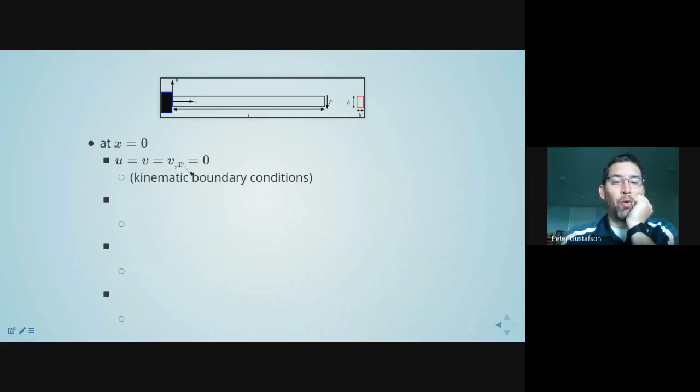And in this case, I'll make one more statement, and that is the slope. This is the derivative of y with respect to x is going to be equal to 0. So slope would be this type of displacement. So it's remaining vertical. We're not getting this sort of shear change, we're not getting a dy/dx at that location.